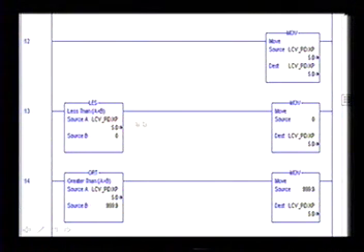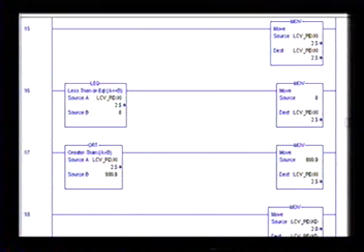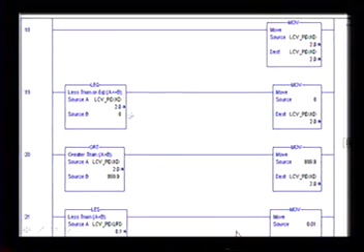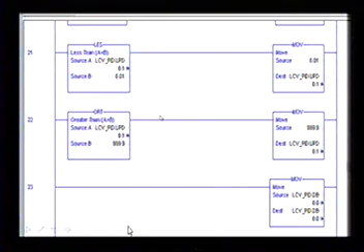And then we do the same thing. So we did data validation on all these variables, right? That way I know that under no circumstances can this PID instruction run if the value .kp is outside of 0 and 99.9, or the min O and max O values are outside of that range as well. I'm also doing all the data validation on the KI here, the KD, and the loop update.